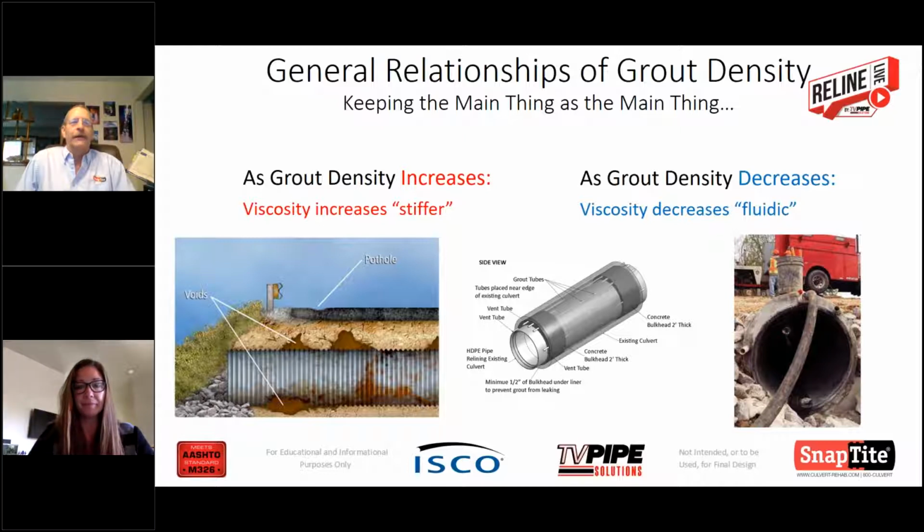In order for infiltration and exfiltration to occur in the existing conduit or culvert, there has to be openings or voids there for the soils or the fill to get in. And then you're using those same voids to try to pump your grout out. Perfect. We've done some studies using ground penetrating radar, using isotopes and x-rays, and also through dig-ups that provide a lot of confidence that we are indeed getting to these external voids.